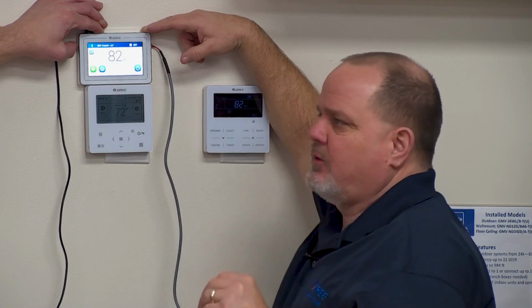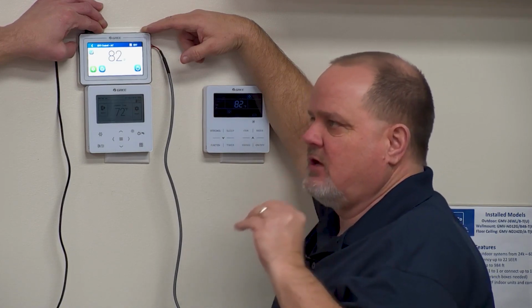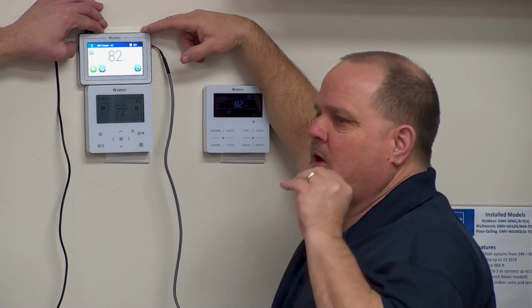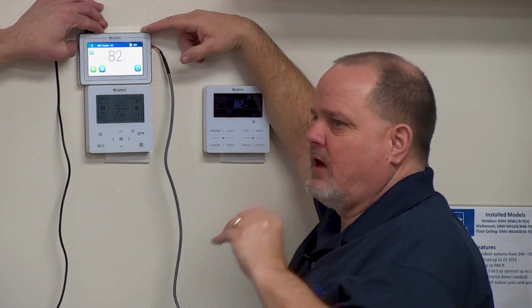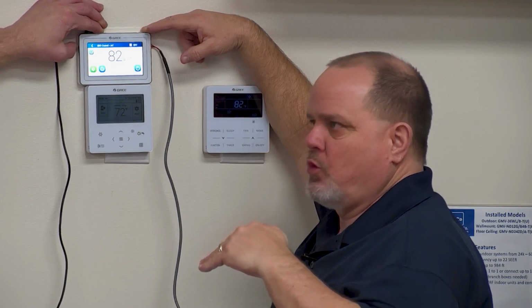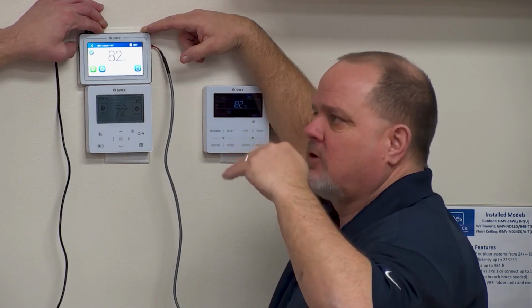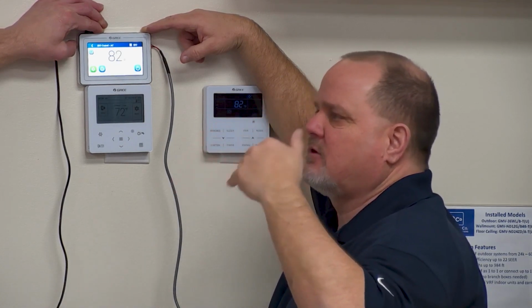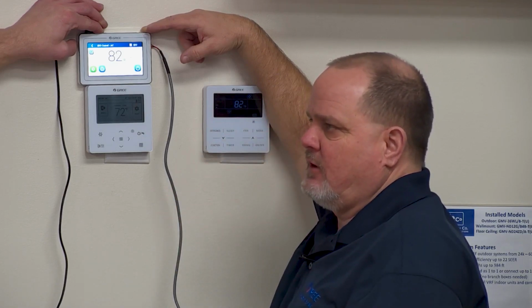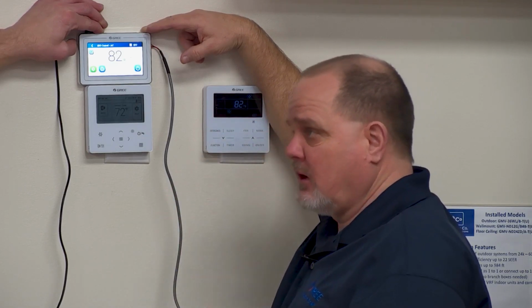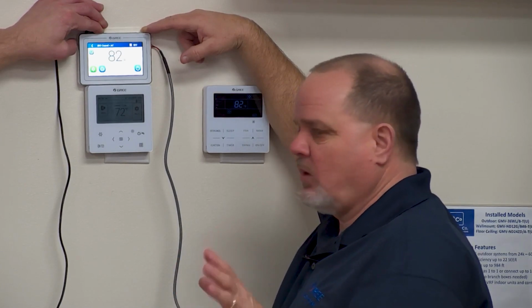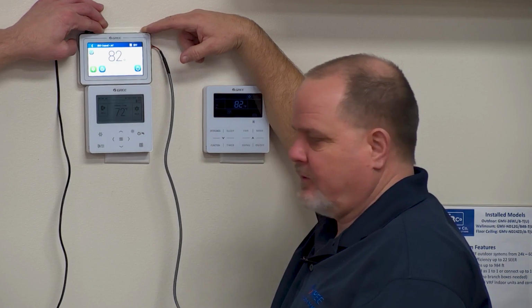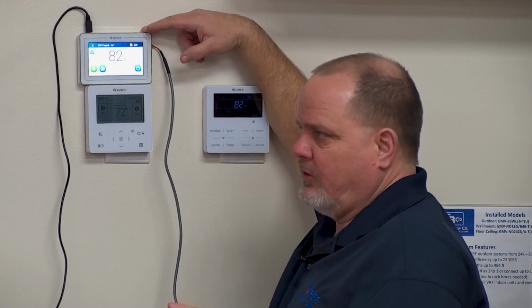And let's say you've got a 3-ton. So it's going to try to achieve 1200 CFM regardless of the static pressure on the machine. So if you've got high static, that blower motor is going to ramp up even harder, trying to overcome the static to keep delivering that 1200 CFM. Whether the motor can actually do it or not is a different story, depending on the ductwork and stuff like that. That's the way variable speed works on standard equipment.